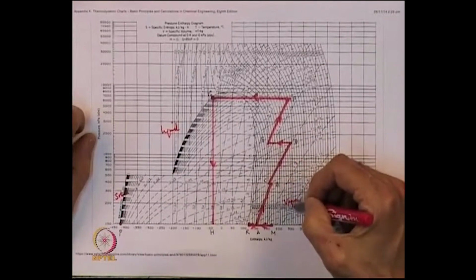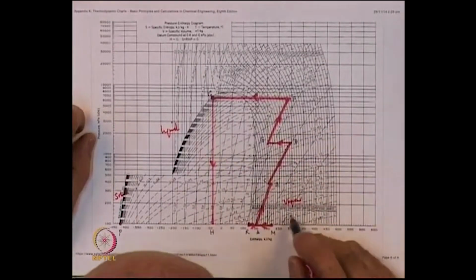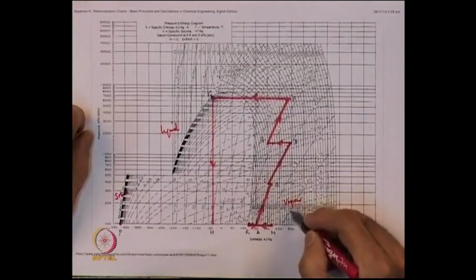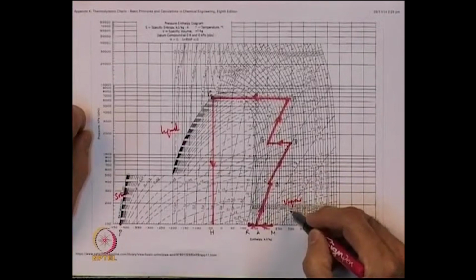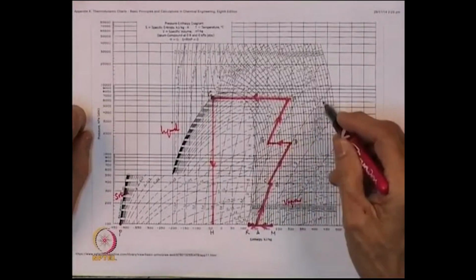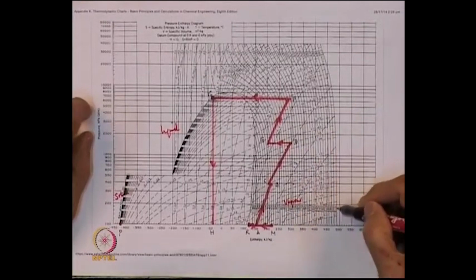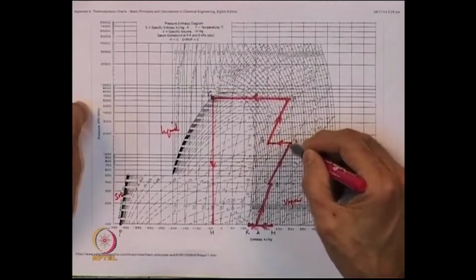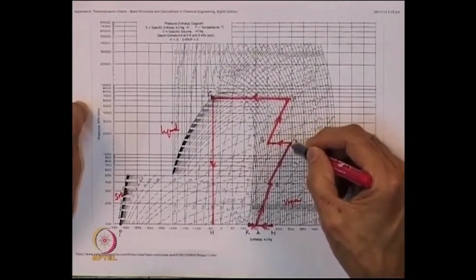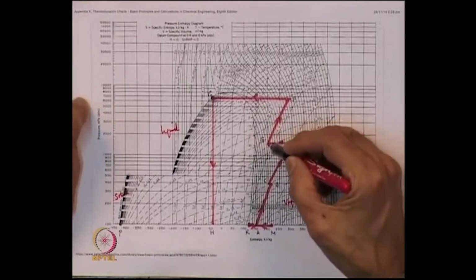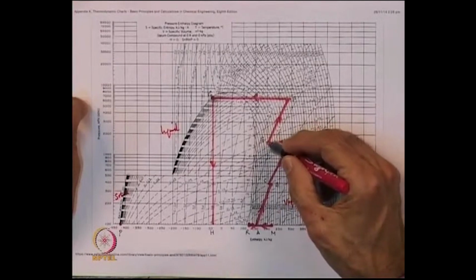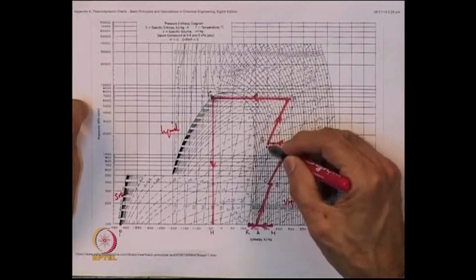In this case, for example, this temperature is like 120 degrees. You can imagine if you keep going, the temperature could rise very high. So, at this point you cool it again to 25 degrees. This is isobaric cooling, just a heat exchanger, and we neglect the pressure drop. So, the pressure is effectively 1600 and the temperature is 25 at the point E.